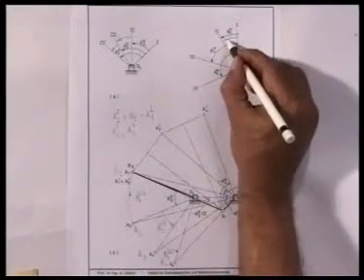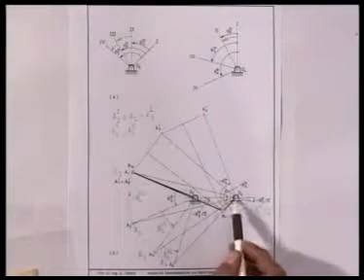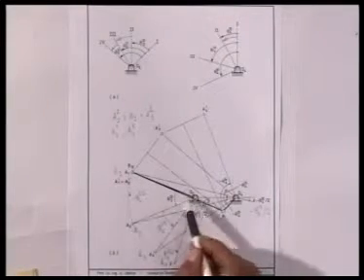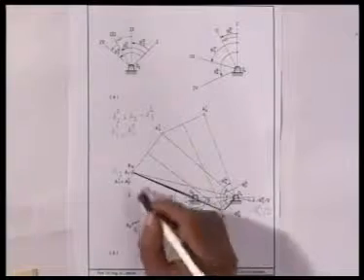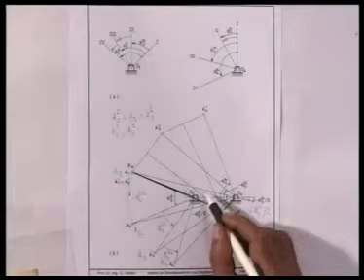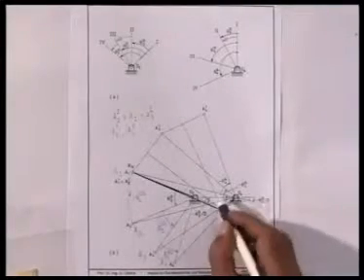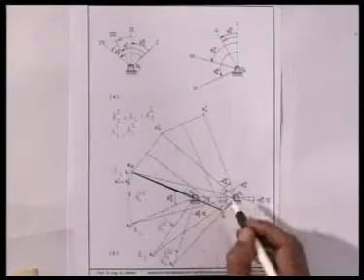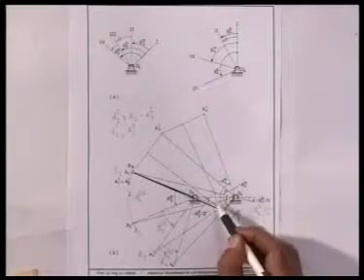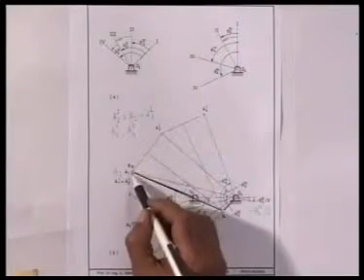This is theta 4 1 2, which is counterclockwise. So, I rotate it clockwise, and because of this, O4 A2 equals O4 A1, O2 A2 is equal to O2 A1, and this becomes an isosceles triangle. O2 O4 becomes the angular bisector of both of these isosceles triangles, and because this angle is minus theta 4 1 2 by 2, this angle, the total angle is theta 4 1 2. Thus, A21 has coincided with A11.